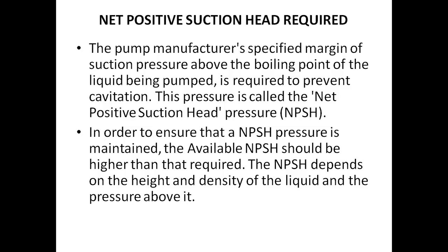This pressure is called the net positive suction head pressure. In order to ensure that NPSH pressure is maintained, the available NPSH should be higher than required. The NPSH depends on the height and density of a liquid and the pressure above it.